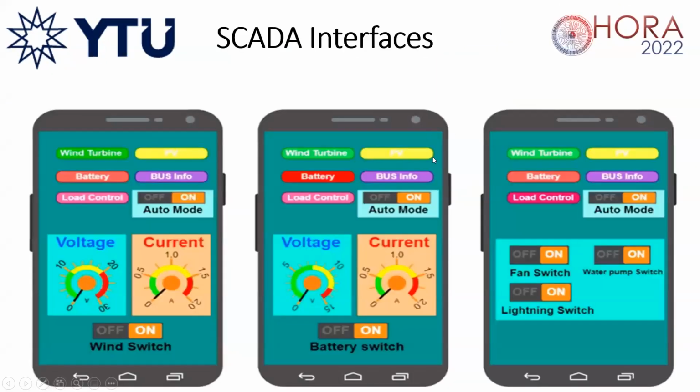Okay, I have explained our system. Now I would like to discuss and show the SCADA system. We use RemoteXY for designing the SCADA interface because it has a user-friendly interface, like, basic, you can see the switch and gauge for parameters. Also, we use it for controlling the system remotely, because RemoteXY has a free web server for sending and receiving real-time data.